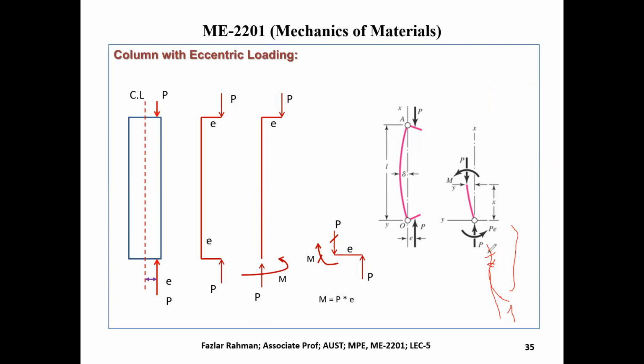So that's why, if you look at this free body carefully, we have this P. Same thing, we put this P toward the bottom direction. Okay. Now we put a moment over here. And the distance between this point and this point is y. And this moment, we don't know which direction. Obviously, it will be clockwise, because what you see, P into E tries to rotate anti-clockwise.